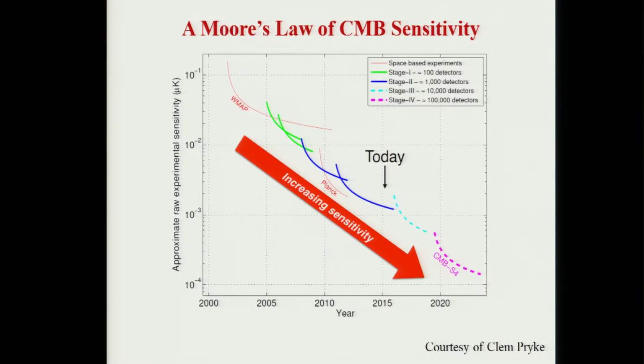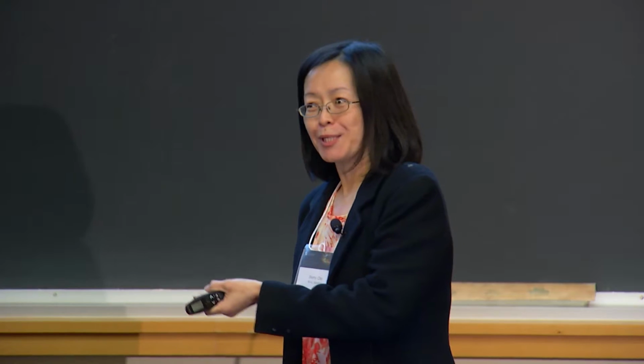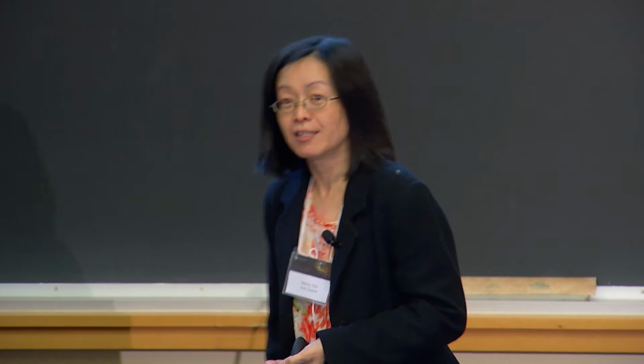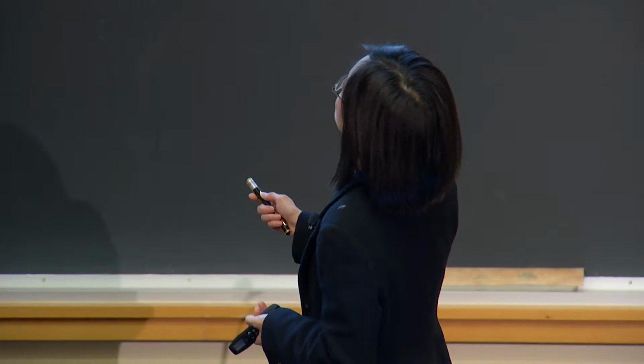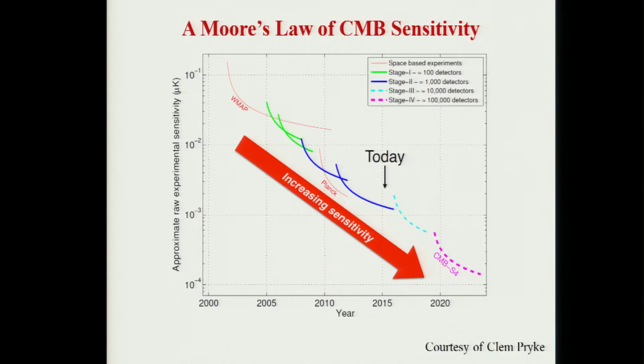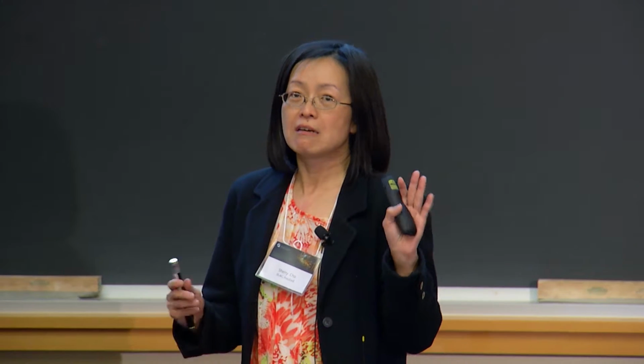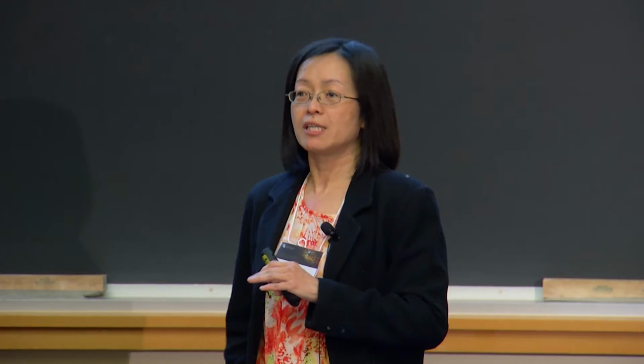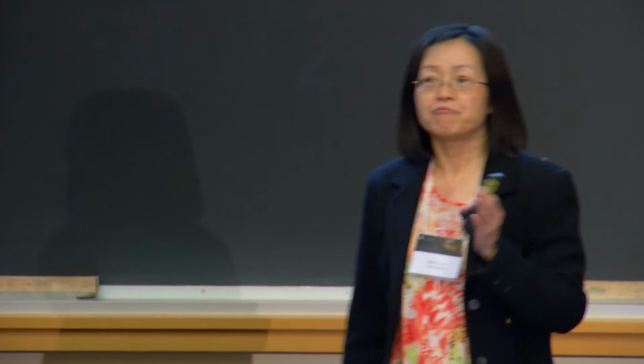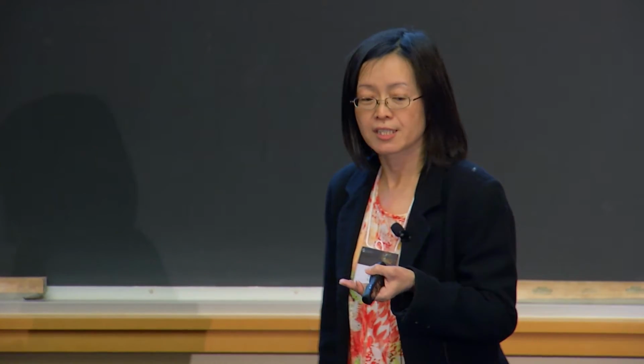And so I went to NIST Boulder. I learned more about TDM, I learned more about FDM, and then we were wondering, what can we do better? At that time, instead of a few hundred detectors, we're looking at thousands to 10,000 now. With the design we had earlier at Berkeley, we can only do a maximum of 8 detectors using one SQUID array. Going to a few thousand gets difficult.